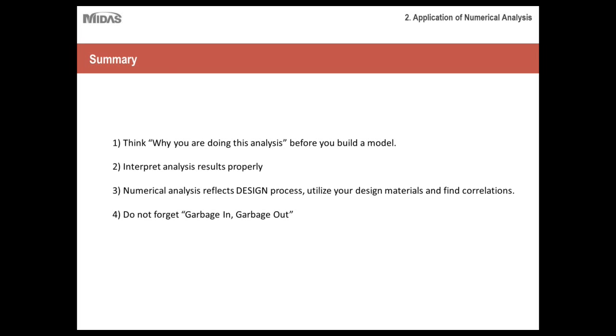And do not forget garbage in, garbage out. As you're starting with numerical modeling, at the beginning you might have issues with results, or you might not understand exactly why you're getting those results. It's really important to go back to the beginning, look at your input parameters, look at what you have in hand, look at the way you modeled the project. Whenever you have any issues with a program or with your analysis, if you go back to your methodology and what you put in, you'll always be able to find something that needs to be changed in order to get a desired result.